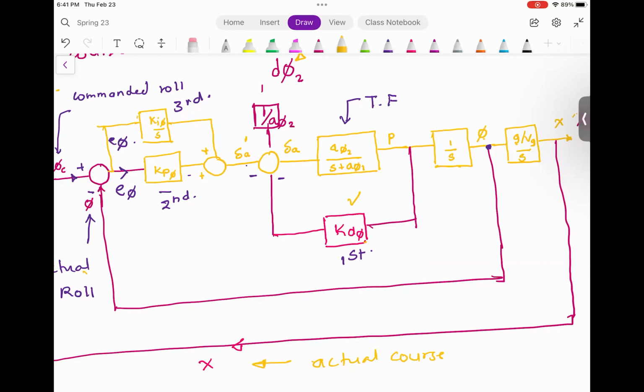So we are adding a little bit more control effort to compensate for the variation in the dynamical system. And that happens all the time, because if you think about it, initially the aircraft is heavy. As the aircraft flies, the fuel is burnt, which means the aircraft mass drops. In other words, the original dynamical equation is no longer valid, which means there is some error coming in because of the variation in the model itself.